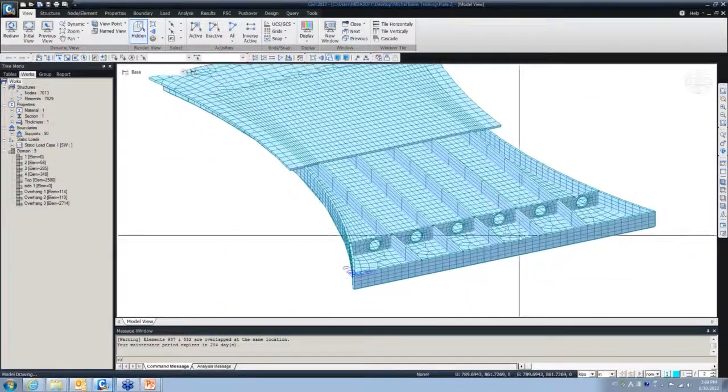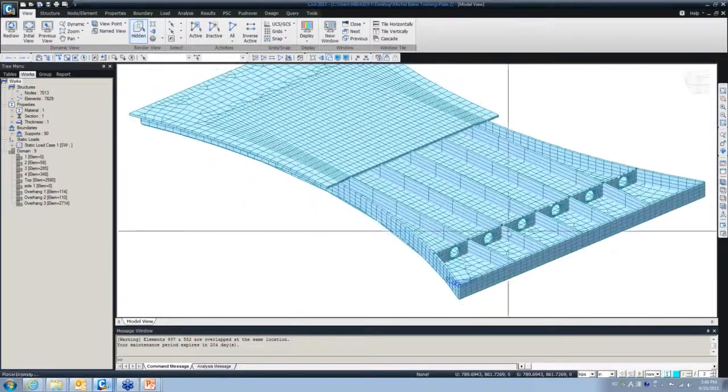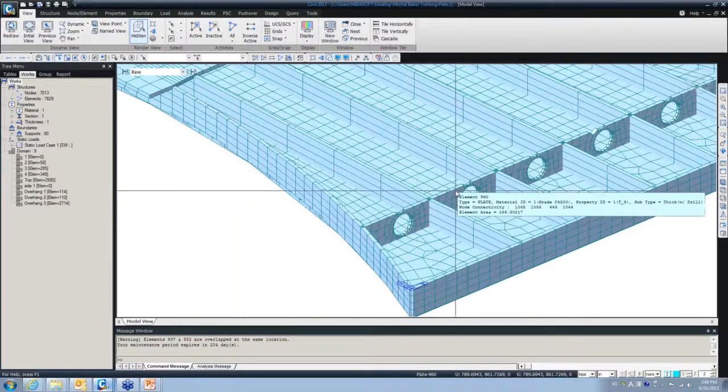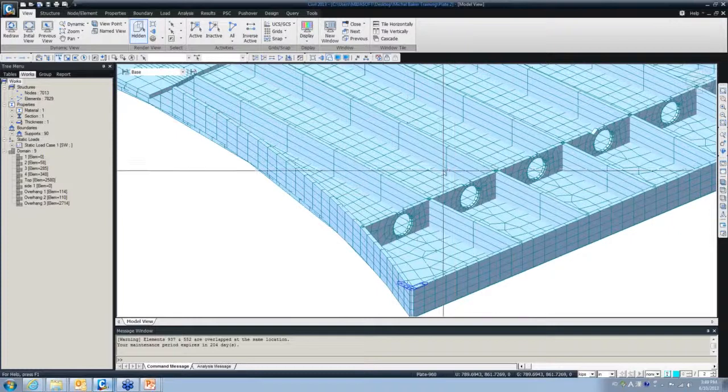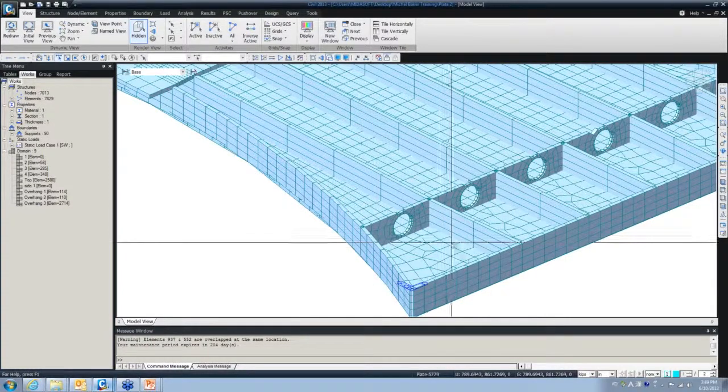I have the stiffeners, I have these openings right here. If I want to post tension the longitudinal elements right here, that's similar to a beam or kind of stiffeners, I can post tension those elements. If I want to post tension the bottom slab, I can do that as well. There is just one thing.